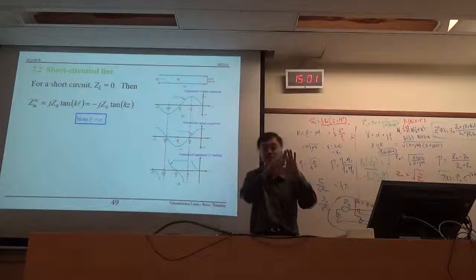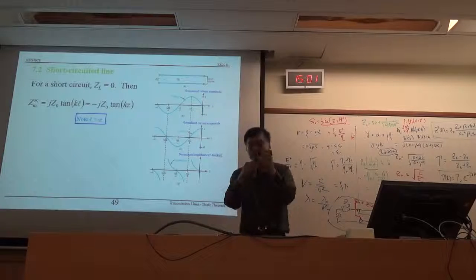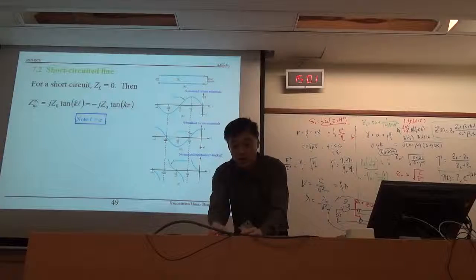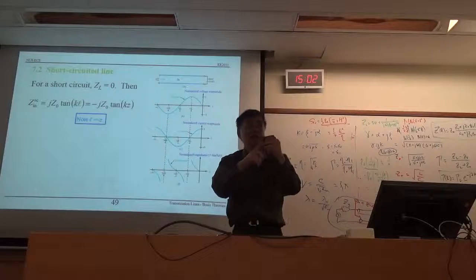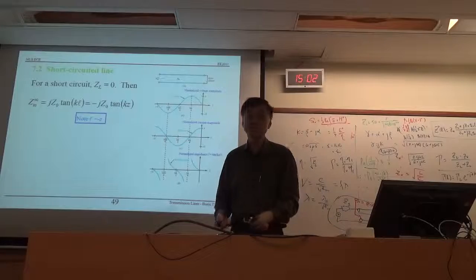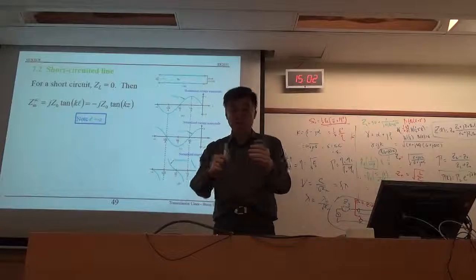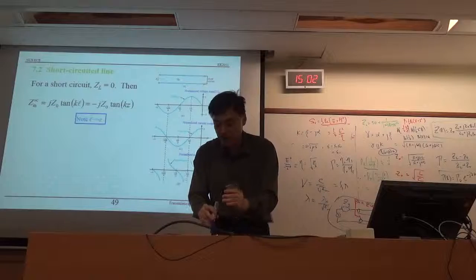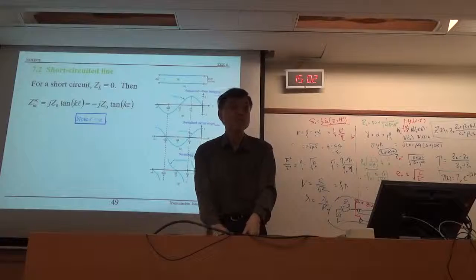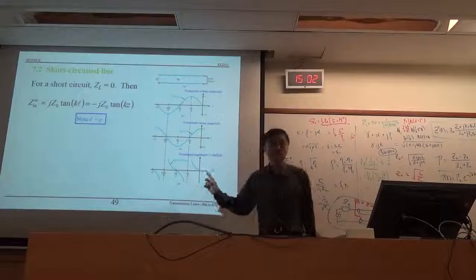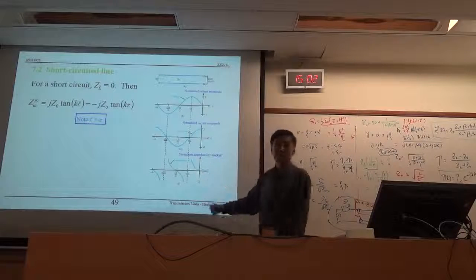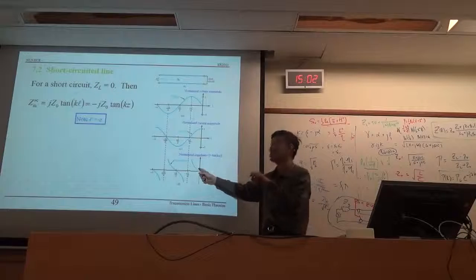If this is the cabinet, you expect it to be grounded like this. You expect this to be ground, but it is not, because the impedance at this point is exactly infinite. So actually it is the same as not doing anything. You might think, I'm grounding it, this is a good ground, I connect a very thick ground wire. No, you don't get it. This is one of the very significant things that a lot of people do not understand. And your grounding impedance can change with frequency.